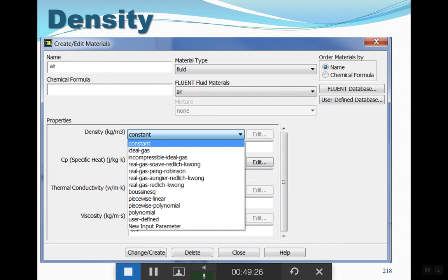And the bad news is your system will not give you any error. It will not give you any hint. It will solve the system because there is nothing wrong with the system. But the only difference is you will not see natural convection. You might ask, if I'm choosing Boussinesq here and a beta coefficient shows up here, doesn't it have a value?